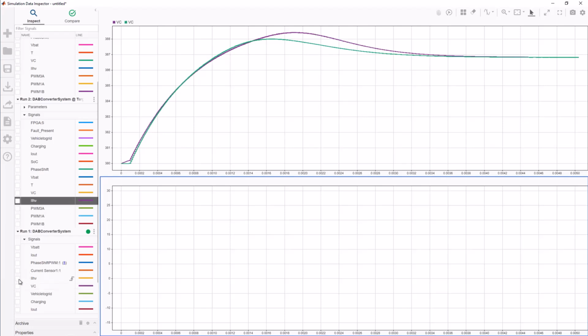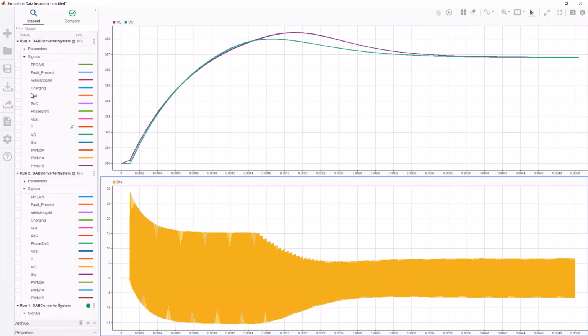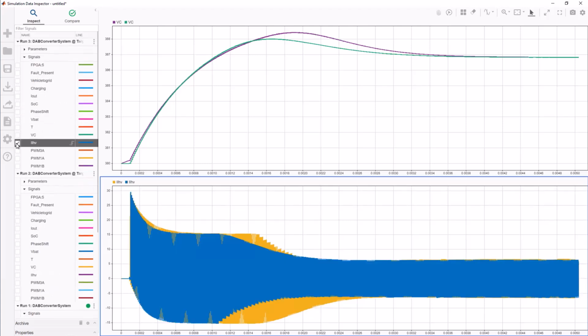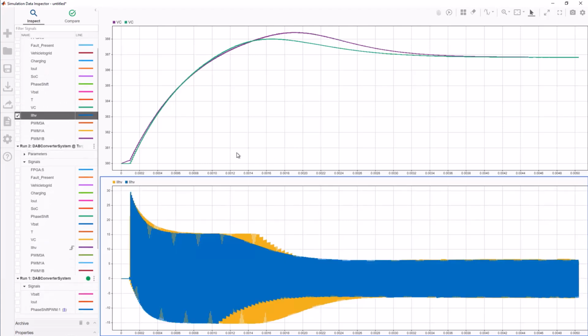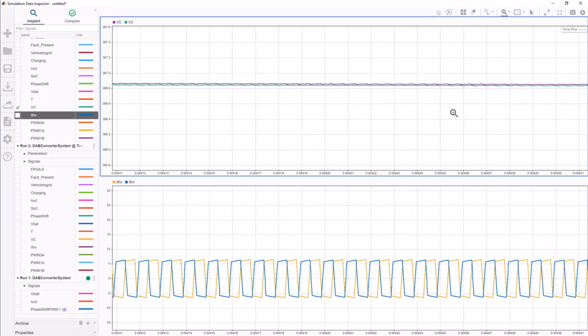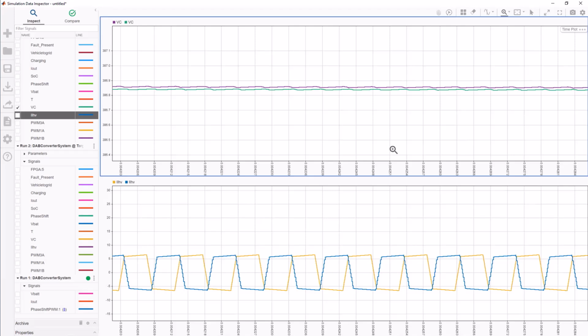Note that some differences are expected between the two designs. The desktop simulation model employs detailed MOSFET models, while the real-time model uses a switched linear fixed-point mathematical model for the DAB's full bridges. You can also use this simulation mode to observe voltage and current switching dynamics with a logging resolution of 8 MHz here.